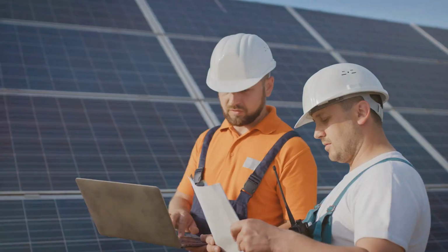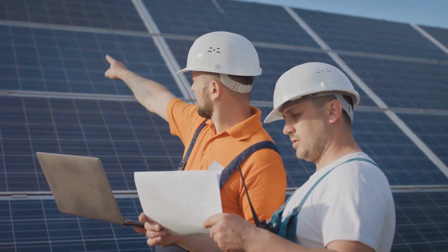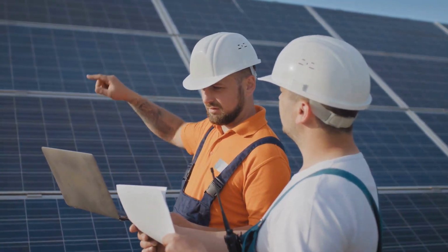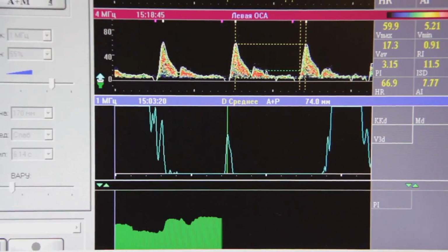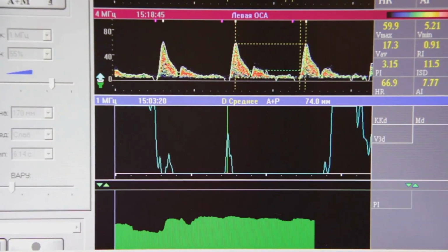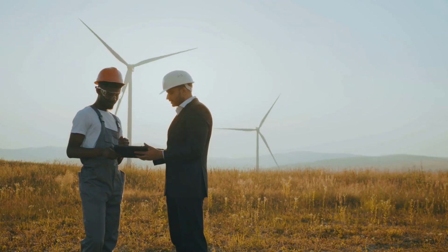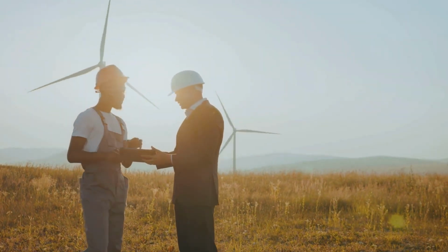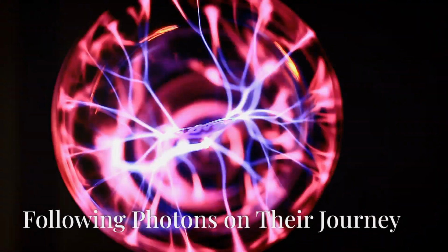However, this accuracy comes at a computational cost. The DO model requires solving the radiative transfer equation for each ordinate direction, making it more computationally demanding than S2S. The number of ordinates chosen directly impacts the accuracy and computational time. Despite its computational cost, the DO model remains a powerful tool for simulating radiation in participating media. It's particularly useful in applications where accurately capturing the directional nature of radiation is crucial.